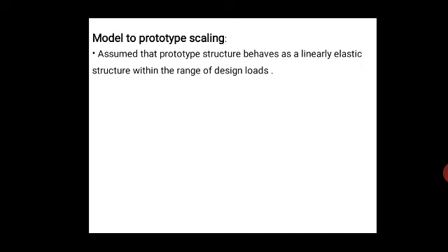See, in the application of the photoelasticity method of stress analysis, it is assumed that the prototype structure behaves as a linearly elastic structure within the range of the loads. So for this reason, many of the two-dimensional bodies which have been stressed have been considered in terms of a prototype model.